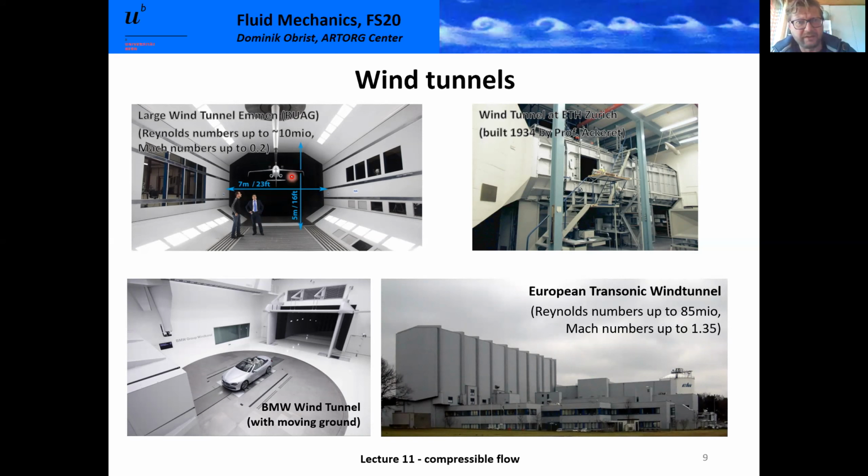It's upside down, hanging off a support, and this support up here is connected to an actual balance, to a scale, which measures the forces, not just the weight force, but also drag forces. Usually it's a multi-component scale, which can also measure torques in different directions, so you get lift and drag forces and also the other components.